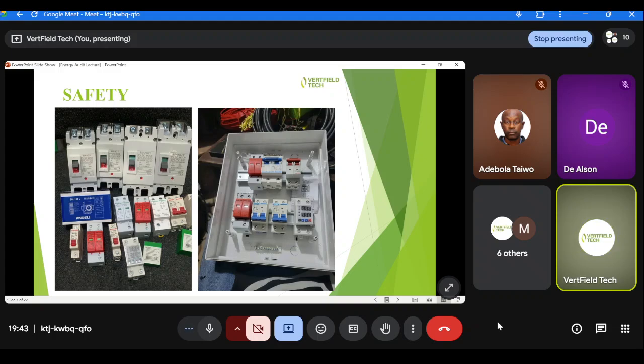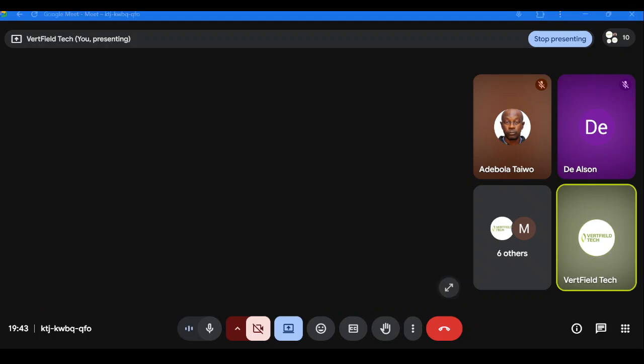If yes, congratulations to you. If no, this is the right place to be. You must ensure that you continue and complete this class, because on no account should you use a DC breaker on your AC side of your solar system. That is the point we are trying to raise here. I hope it is clear.